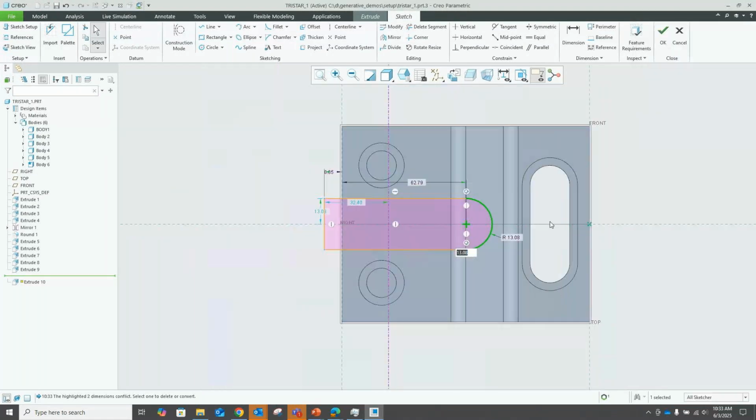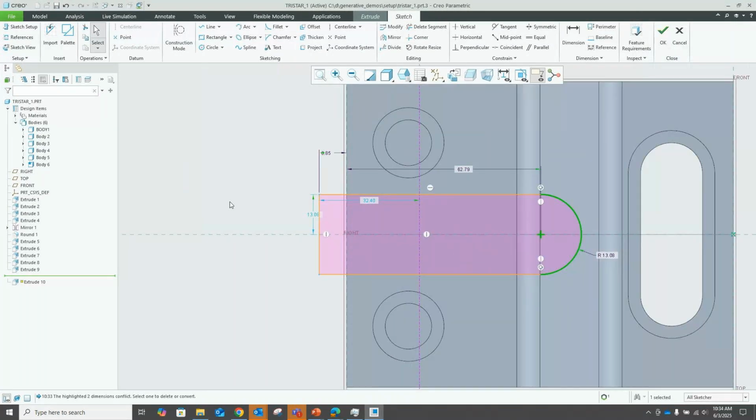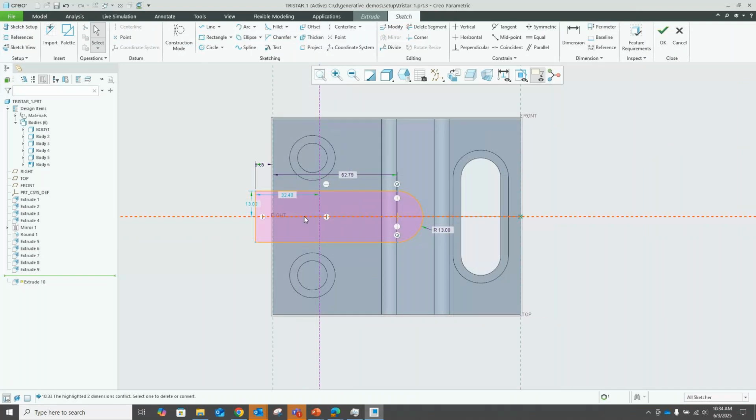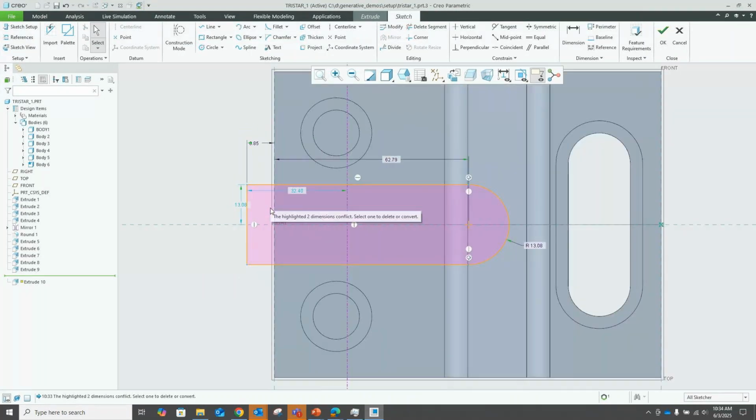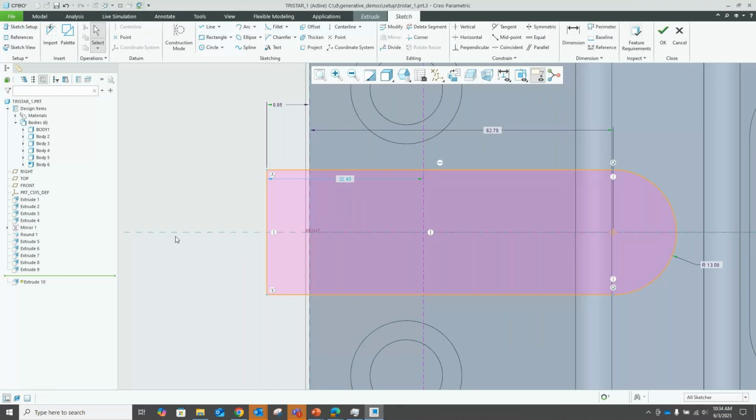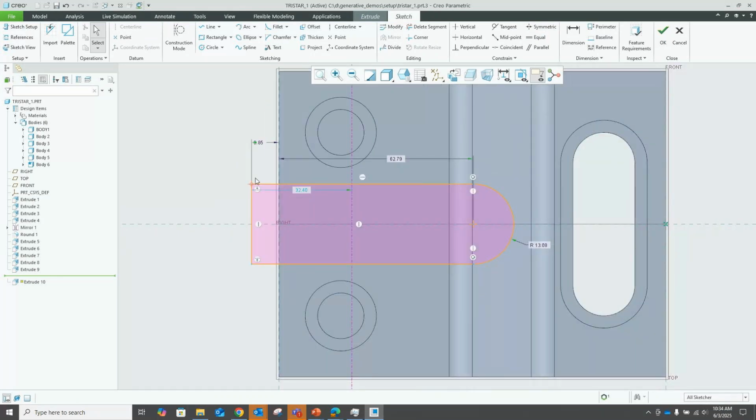Right there, and looks like, yeah, okay. So with this, maybe I want to make sure that it's kind of working around it. Maybe we'll just specify some symmetry constraint about this also, maybe off of these two. You no longer need a center line for a symmetry constraint. There's a cool enhancement in Creo 7 that some of you might like.